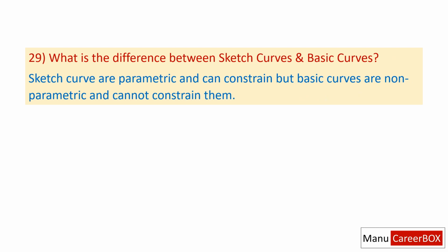29. What is the difference between sketch curves and basic curves? Sketch curves are parametric and can be constrained, but basic curves are non-parametric and cannot be constrained.